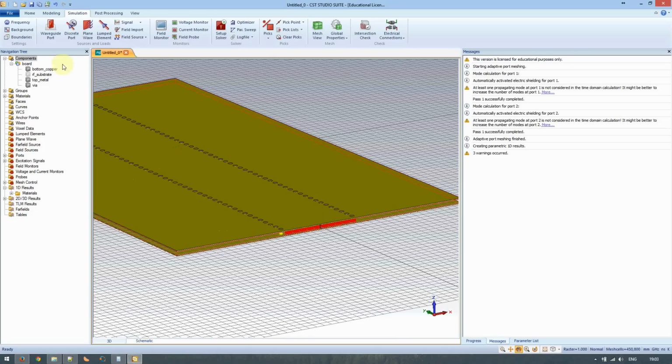If your frequency range of the simulation is below the cutoff frequency of your SIW, then the energy will just sort of bounce back and forth. The waveguide will cut it off. It won't propagate down the waveguide, and it'll just bounce back and forth here in a sort of resonant kind of structure, which means that the time domain simulation will take a very, very long time. So you want to check that you are operating above the cutoff frequency before you set up the solver properly.